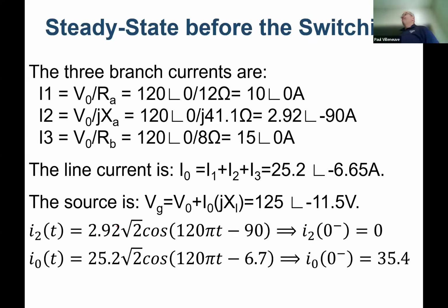Yeah. Not the other way around. So I have to put the square root of 2 in because what we do in our wall sockets is we have 120 volts, but in actuality, the voltage hits almost 170. That's the peak magnitude. So if you actually monitor the waveform, you wouldn't see 120, but you would see 167 as the peak, a couple times a cycle.